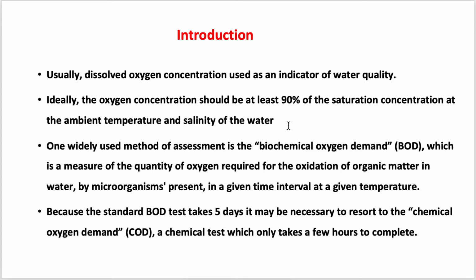Okay, and there are different methods to measure the dissolved oxygen concentration. One is BOD, biochemical oxygen demand. BOD is a measure of the quantity of oxygen required for the oxidation of organic matter in water by microorganisms present, in a given time interval at a given temperature. However, measuring the BOD takes time. It usually takes 5 days.